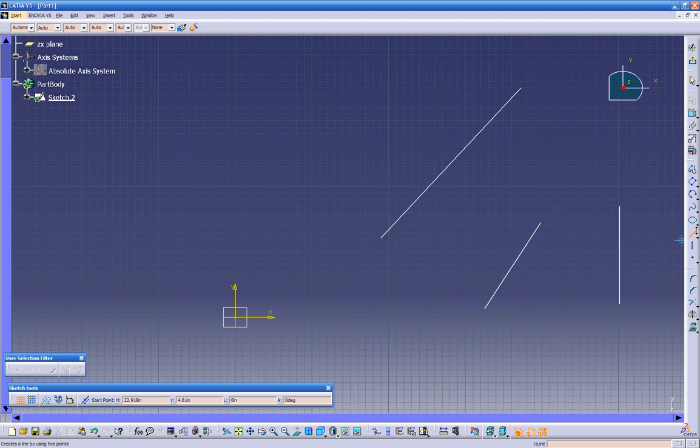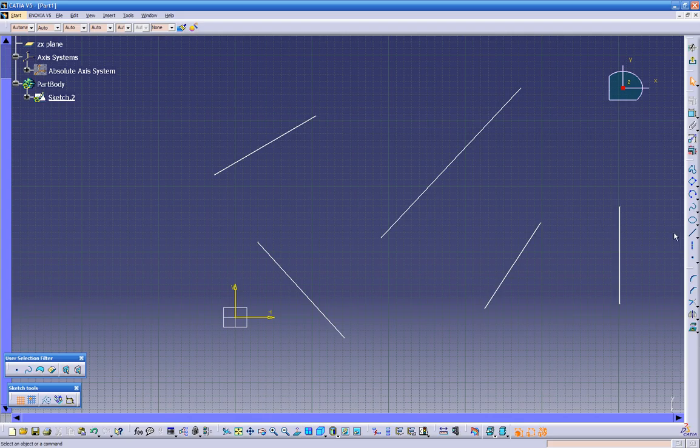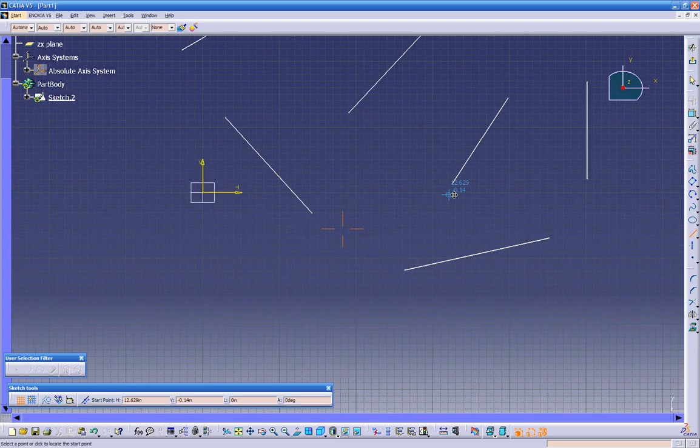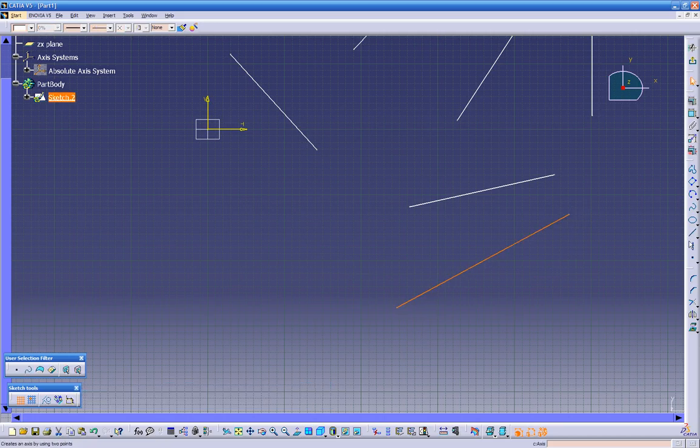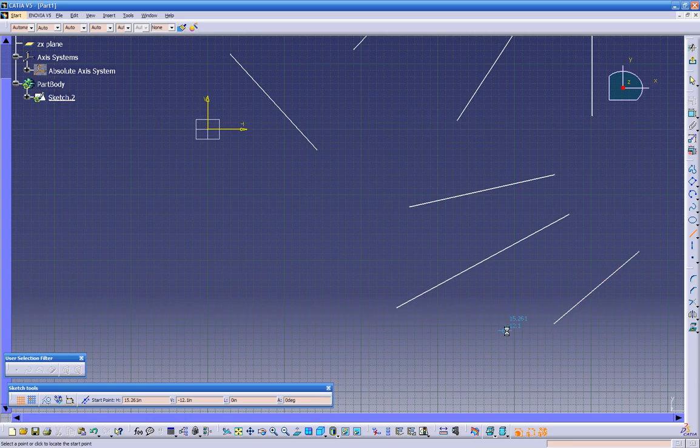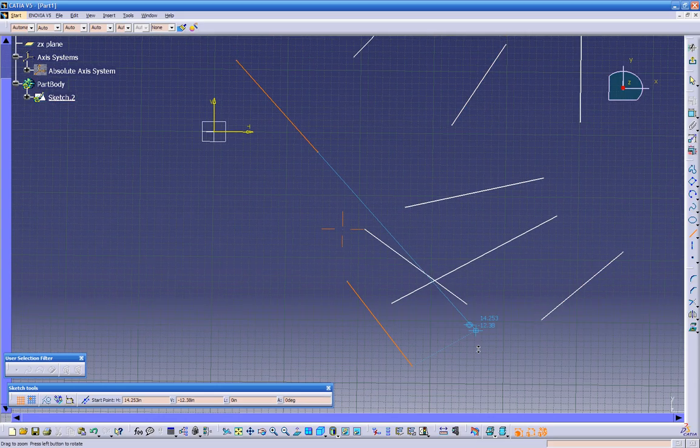If you watch this icon right here, it's activated. As you see, it stays brown. So we can keep creating lines. That way we don't have to go every time and click each line individually. See, right now I'm doing it only once. See, it deactivates. So if you double click, you keep on creating lines, which is very handy.